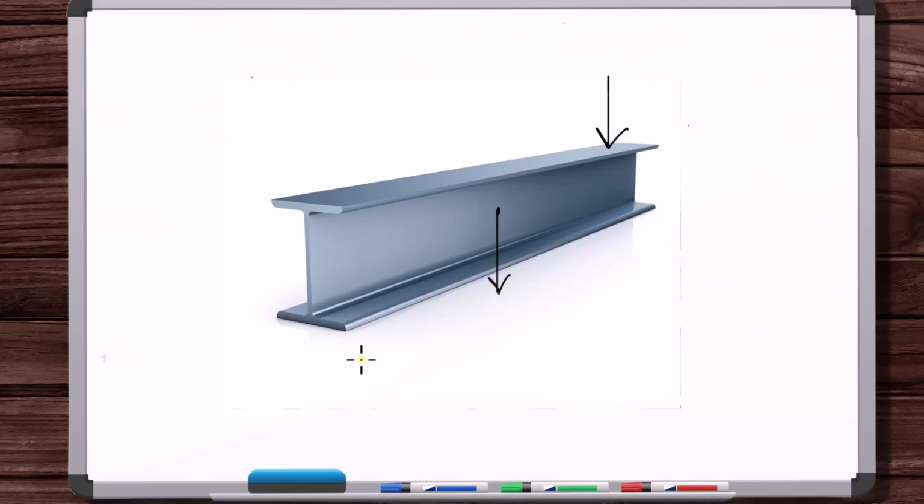All right, so there's no electricity and magnetism to deal with here. So then we look for what? We look for points of contact between the beam and its surroundings. Well, we're not imagining that this was unbolted. We're just treating this as a free end with a force here. There's a contact here, so we put that point load because the area of contact is small relative to the entire beam, so we have this point load here. There's no other areas of contact or points of contact anywhere on the beam.